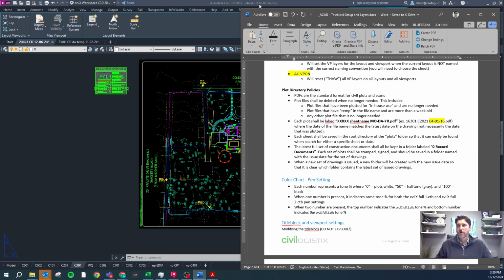So when I get out of this drawing, really probably before I should open this up, I should have just changed this 06 to 1/2, so it'll be 12/24. We don't want to have things with real old dates in there, because there ends up being, over time, additional drawings get in there. We really only want to have one AutoCAD file, but there ends up getting more. So if you can be diligent about keeping the current date on there, then that'll be very helpful for everyone.